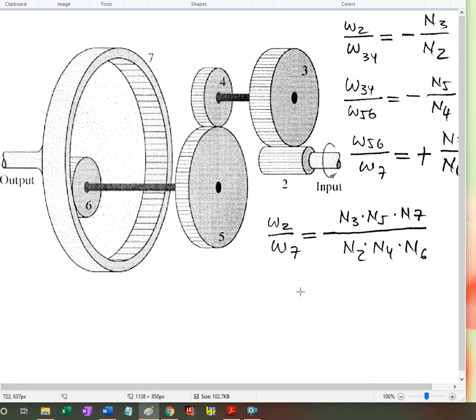So I want to know the transmission ratio between input and output, again I want this to be red, and which direction they rotate. Well, we can analyze just that, and I'm sure you did this in maybe high school. So one, the opposing direction, the same direction, this one opposing. So this is moving in this direction, the same as number 6 because it's internal gearing.